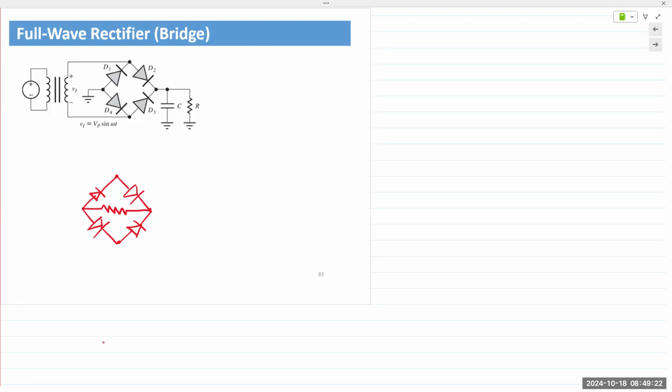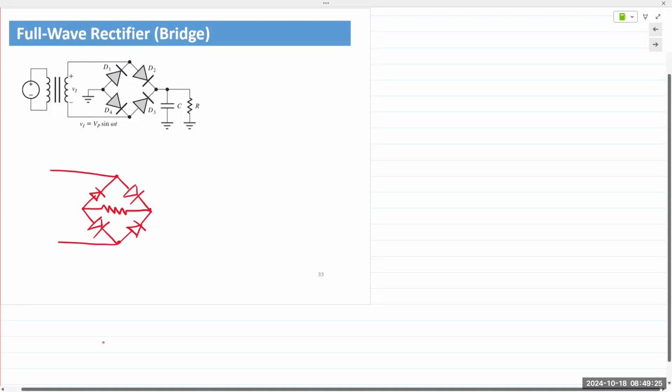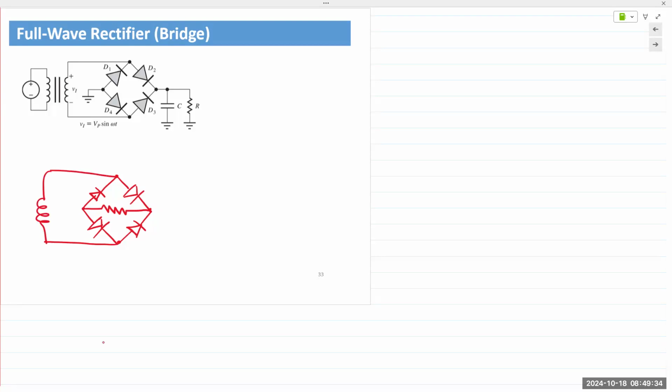And so this is where we would supply our input. Okay. So again, 4 dots, make 2 diodes pointing up, 2 pointing down. And then once you have your rectifier circuit, you should ensure that you have 2 anodes and 2 cathodes, and then 1 anode, 1 cathode at 2 terminals. And that's how you know your rectifier diagram is correct.